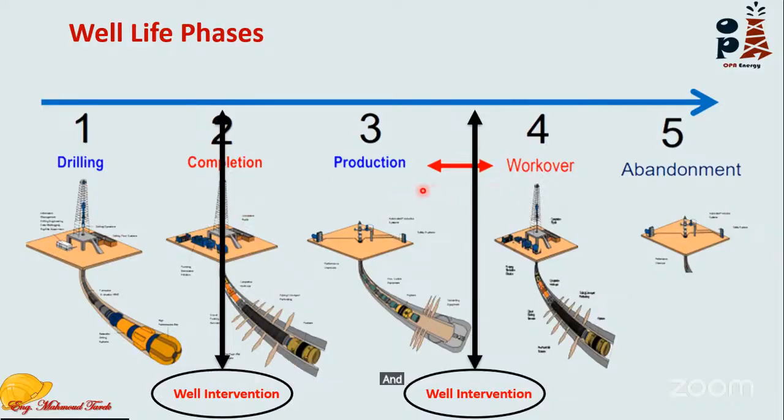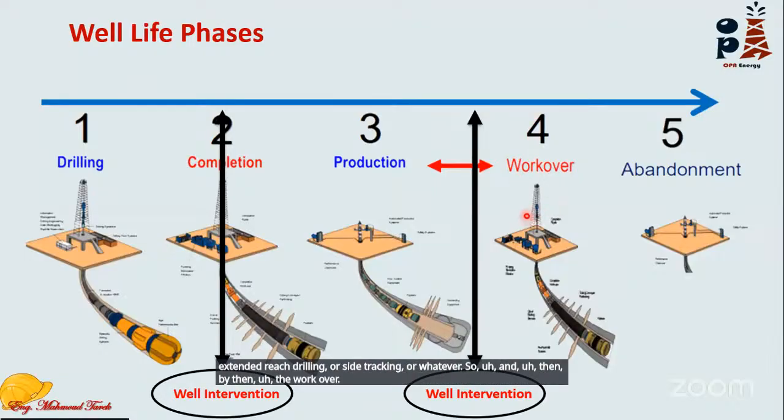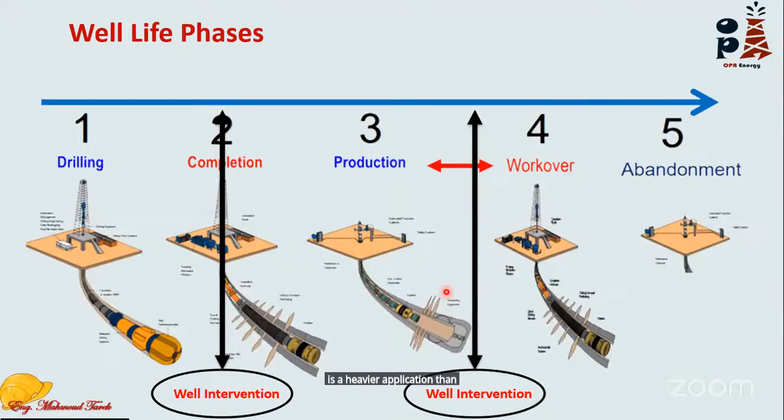And by the way, if the problem can't be resolved by the well intervention technique, we may introduce a workover. The workover here, we will bring a rig. This rig will pull the tubing and solve the problem, the integrity problem, or deepen the well by extended reach drilling or side tracking or whatever. So the workover is a heavier application than the well intervention.